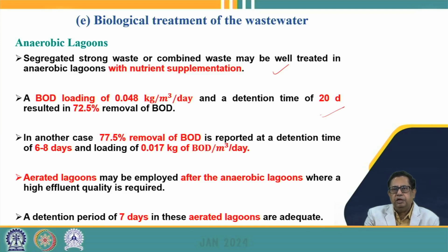It has been found that if we have a BOD loading of nearly 0.048 kgs per cubic meter per day and a retention time of 20 days, it can result in nearly 72.5% removal of BOD. Similarly, another case reported nearly 77.5% removal of BOD at a retention time of 6 to 8 days and a loading of 0.017 kgs of BOD per cubic meter per day.